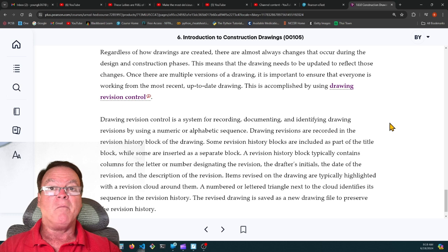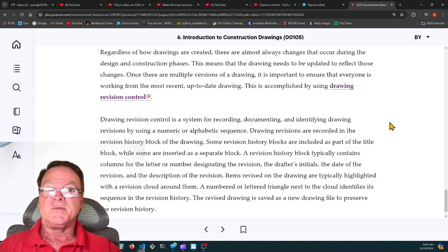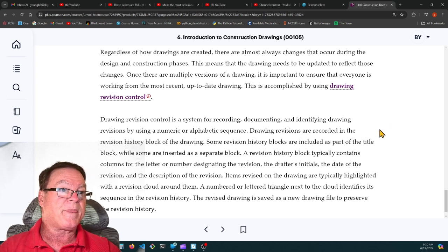Someone will think of something a month down the road and they'll say, oh, you know what? We need to put in an outlet here for a hot plate so that when we're serving out in the dining room, we can prepare things or keep things warm while we're serving the customers. All right, well, let's do that. That's a revision. Let's draw it in. Let's give it its own circuit number and bring it back to the panel.